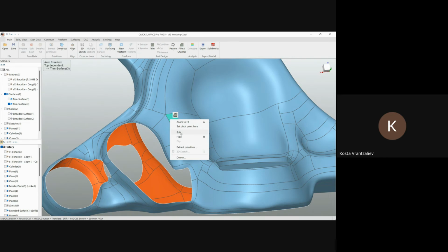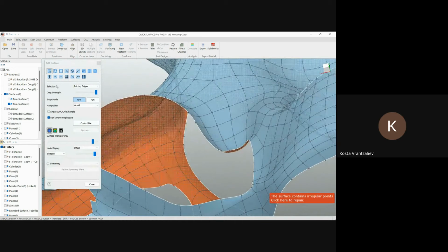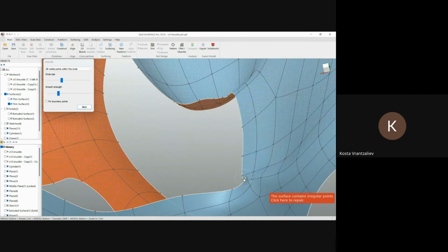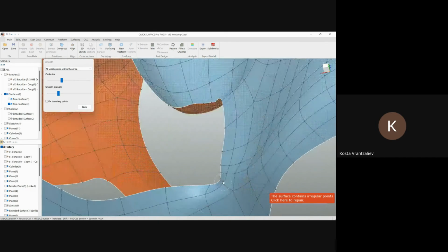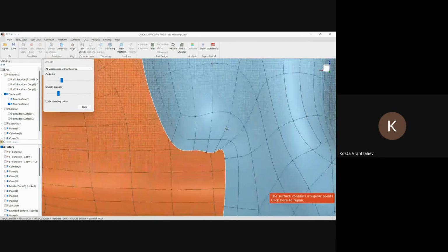So like Victor showed, make sure that this surface goes completely over the others. In the CAD industry, these B-splines, etc., may cause a lot of problems. And if in your project you find that this trimming doesn't work, just make sure that you have enough excess of the surface so the trimming can work.